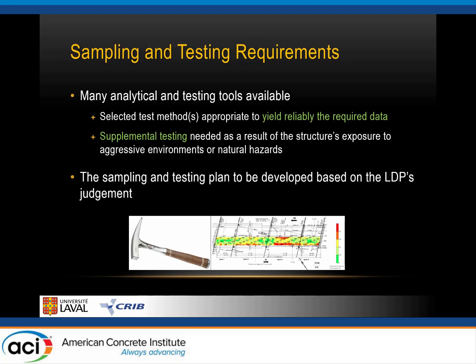And it goes from very simple approaches, like Ashok was showing, for sounding the surfaces, to much more complex and sophisticated techniques to get an insight of what's going on inside the elements. Like ground penetrating radar, for instance, to evaluate the delamination over a concrete deck.